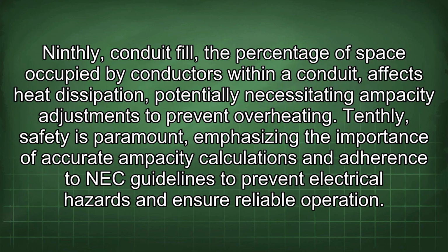Ninthly, conduit fill, the percentage of space occupied by conductors within a conduit, affects heat dissipation, potentially necessitating ampacity adjustments to prevent overheating. Tenthly, safety is paramount, emphasizing the importance of accurate ampacity calculations and adherence to NEC guidelines to prevent electrical hazards and ensure reliable operation.